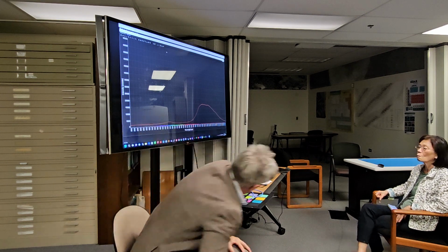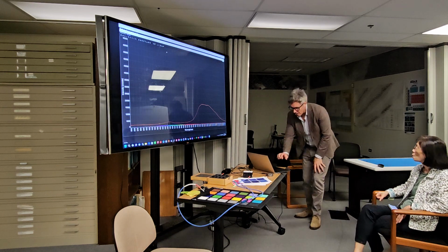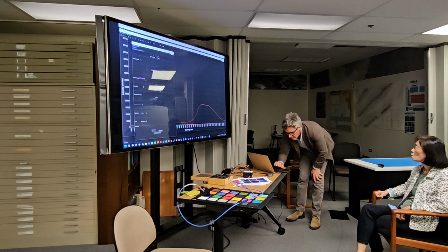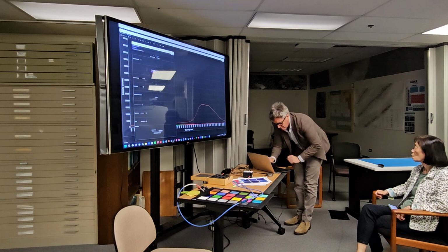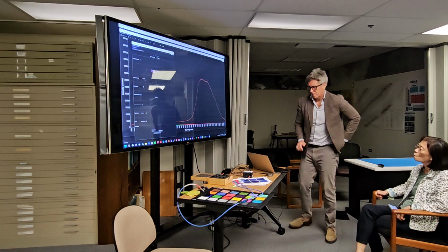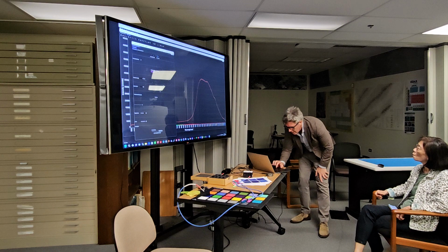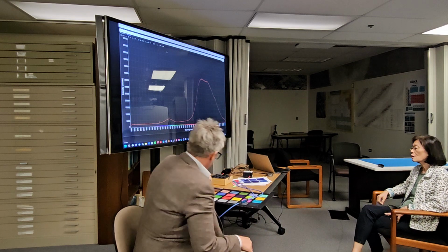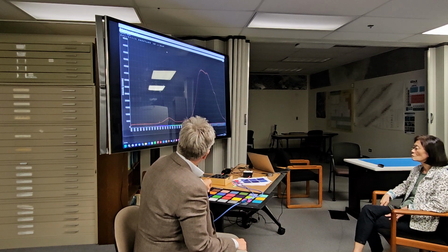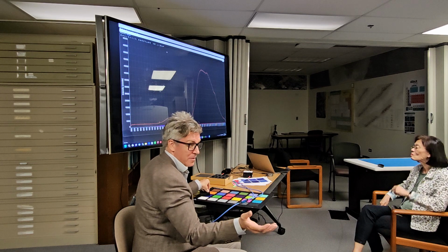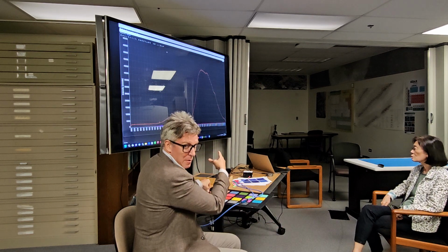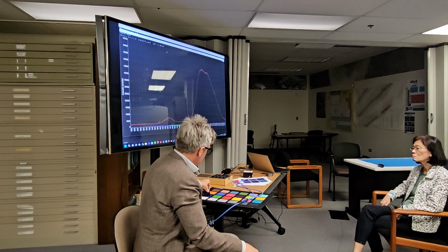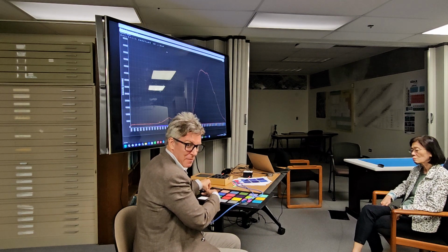Now I can make that look a little bit better, to make you feel a little bit better, by increasing the integration time. Right, so I got a bit more of a bump in the blue. Okay, so what you said holds, at least as far as the visible spectrum is concerned. We've got this big peak in the infrared, but if we're interested in measuring visible light, we don't care about that. What that's telling me is the paper is very good at reflecting infrared light.